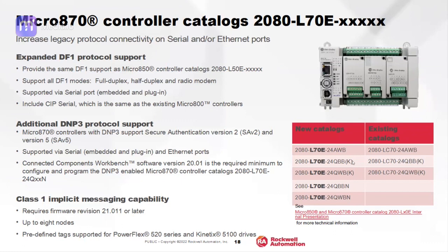With PowerFlex 520 series drives, Kinetix 5100 drives, and point IOs, in either combination, we can use up to 8 nodes through class 1 messaging. Earlier, if you wanted to communicate with some other PowerFlex drive over Ethernet, we needed to do some messaging programming. Now you can easily just add it into the tree and configure.